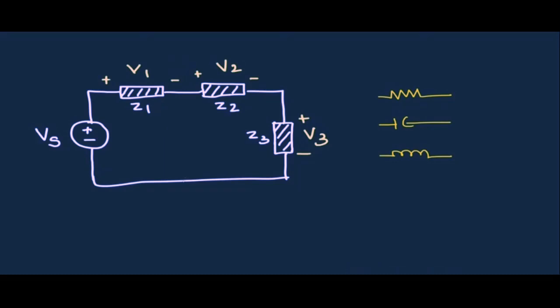According to Kirchhoff's voltage law, if we move around this electrical circuit and add the voltages that we come across each element in the circuit, then their algebraic sum is 0. Let us say we are moving in clockwise direction starting from this point A, and the first element that we come across is this voltage source Vs, and we are moving from negative to the positive potential.